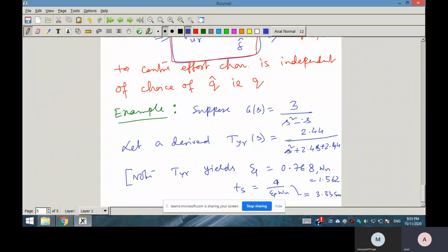So here we want a settling time less than 4 seconds and zeta less than, say, 0.8, just near 0.77. This will obviously give very good behavior of the closed loop system. So this is the reference input to output model I want to match using 2-degree of freedom control. Then what is my flexible parameter?